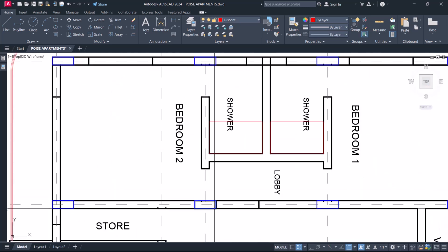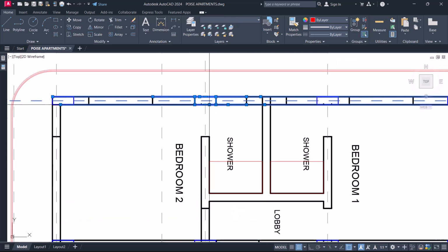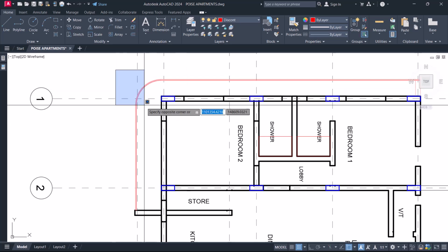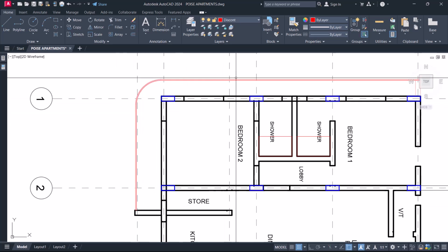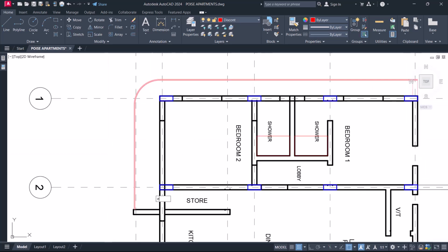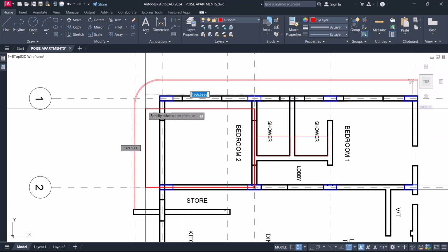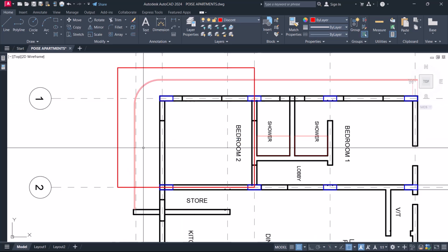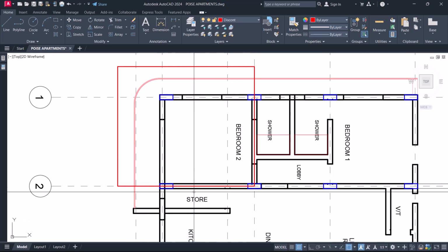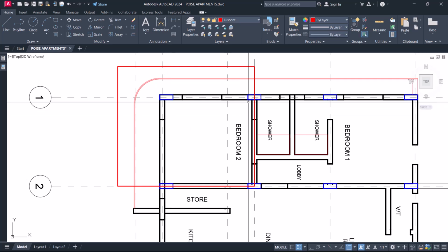Okay, so this can extend here, and this can extend here. Okay, so this can be our slab area, that's from this curve up to this point. This can be one of our flat slab areas, from this midpoint up to all these parts. This can be one of the flat slab areas that will be carried by this column, this and this other area.